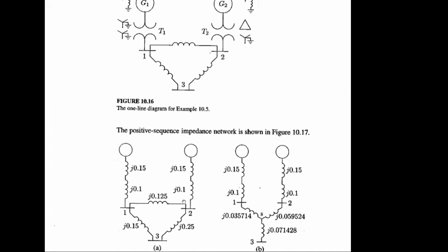Here you can see the difference. The positive sequence transformer equivalent circuit will not have any impact from the internal configuration. Okay, remember that. Only the zero sequence transformer equivalent circuit has the internal circuit issue. Okay, sir.